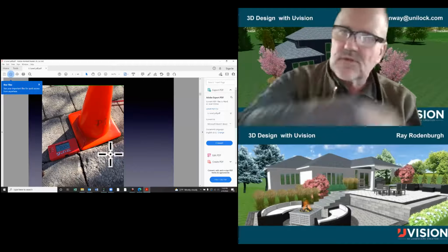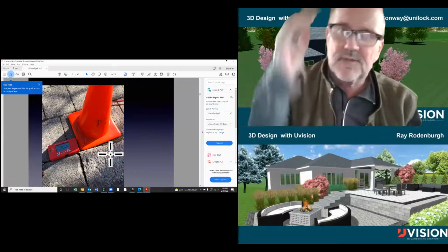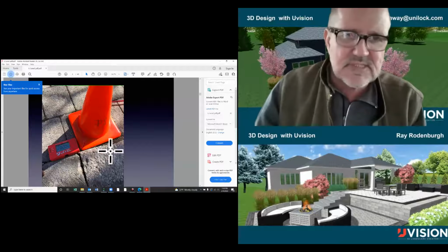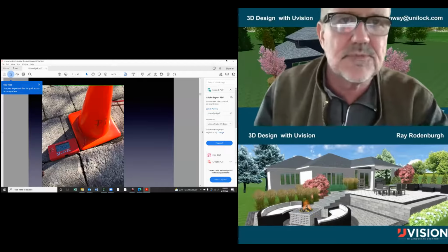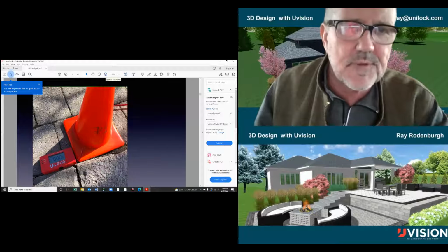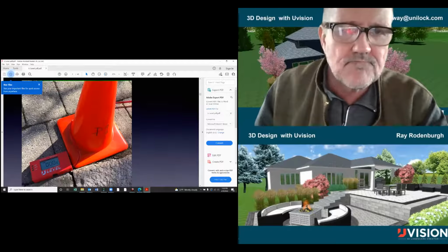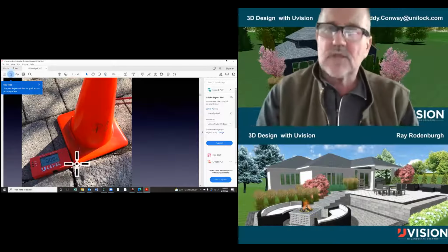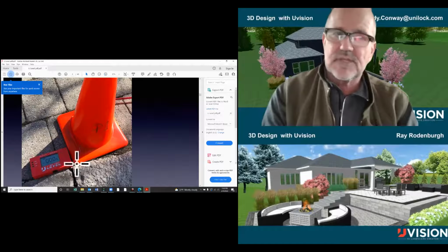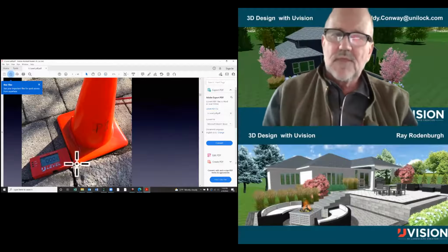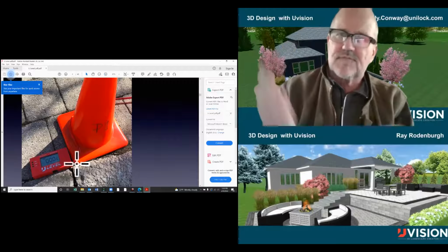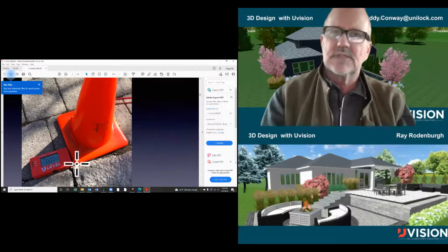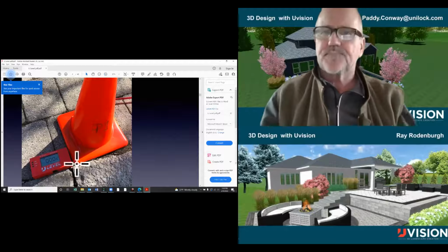Because when you come back, you're going to do a circuit and come back to where you started, and the readings should be the same. If I'm reading a 16th of an inch on the screen as my starting point, fine. As long as I come back and there's a 16th of an inch on the screen at my final reading, that means it was a perfect circuit and I started and finished on the same point. Now, if I come back and there's an 8-inch difference, something's gone wrong. You have to redo it again.